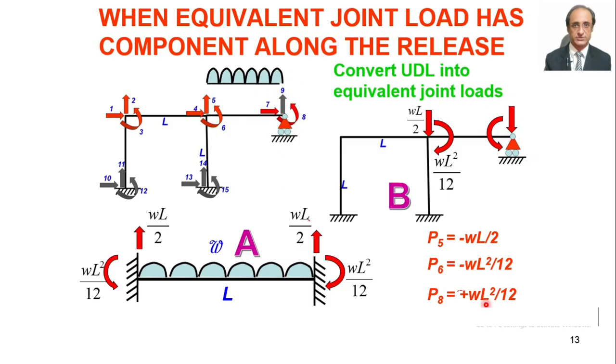So we'll have X minus WL by 2. So X9 also gets an additional term. This we have already seen through solved example, that when we write X9 we have to write it as X9 minus WL by 2, so that when we get the final solution, WL by 2 will go on the right hand side and it will be added.